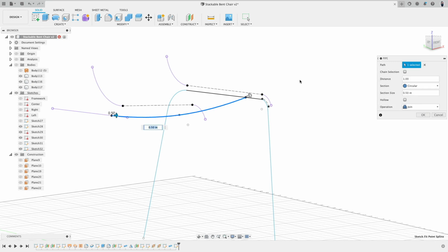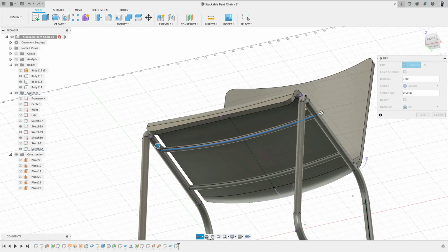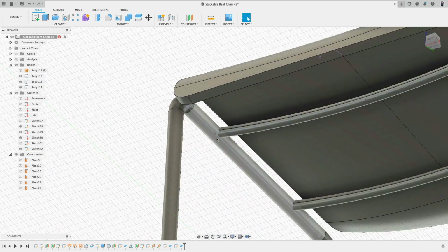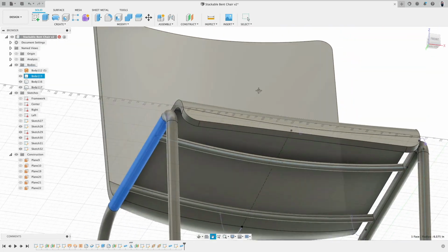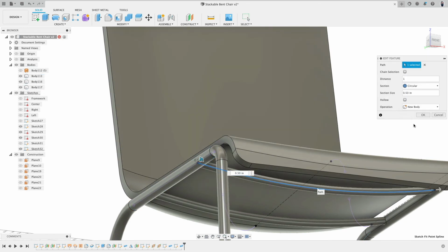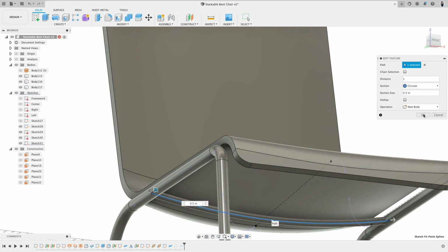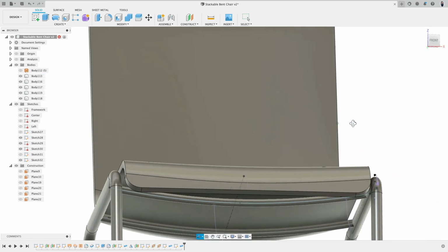Pipe here again. Yeah, maybe show the 2 parts. Okay. I notice actually here it does not join. You see this? These are not joined. So because we may have to do a manual join afterwards, I will quickly go ahead and change each one to just new body. So I just double clicked on each feature.